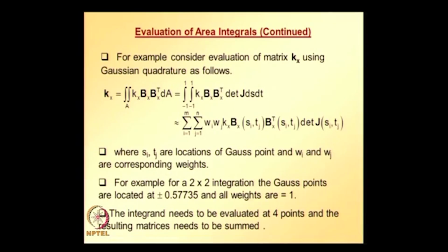First we need to express this Kx in terms of S, T before we go ahead with numerical integration. How to express Kx as a function of S, T? For that we need to use isoparametric mapping, which relates x, y to S, T.